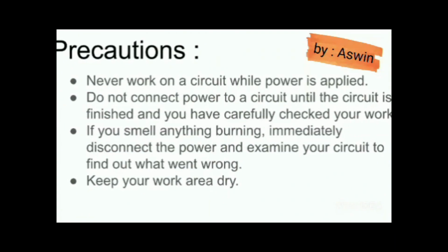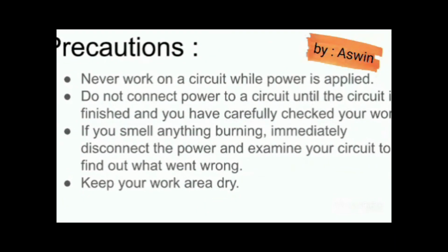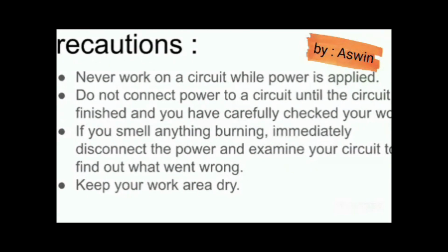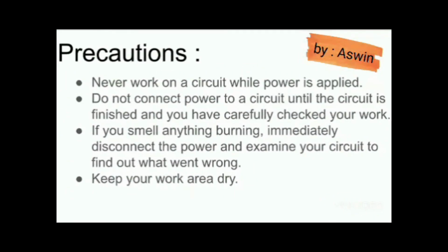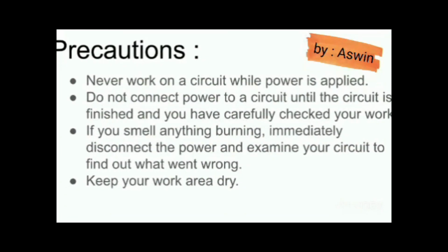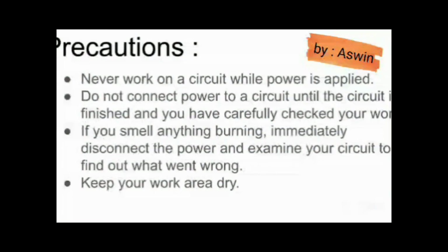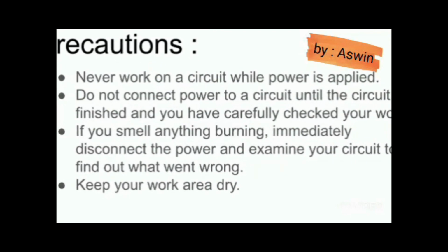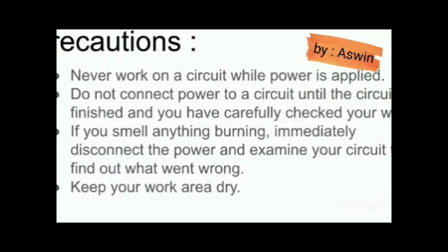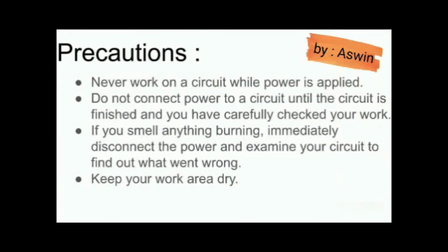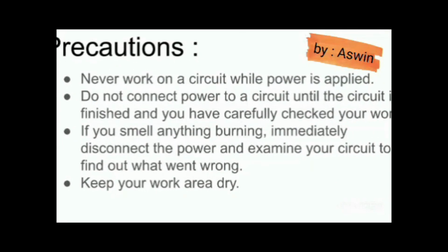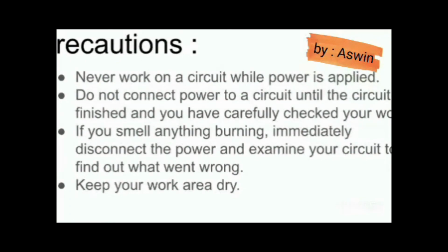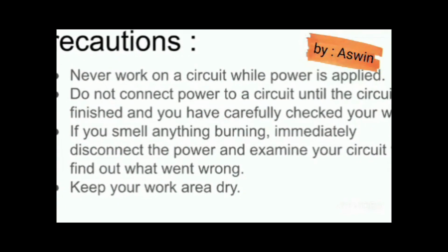Precautions. Never work on a circuit while power is applied. Do not connect power to a circuit until the circuit is finished and you have carefully checked your work. If you smell anything burning, immediately disconnect the power and examine your circuit to find out what went wrong. Keep your work area dry.